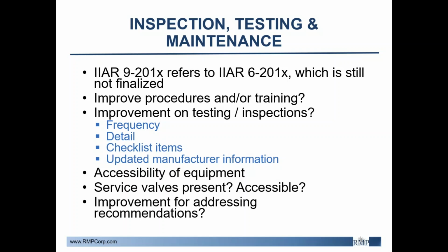If there's a way to do that, there's a way to improve testing and inspections based on frequency or detail, or adding things to your checklists to make sure that all the equipment's being hit, or maybe there's known faulty valve types that you need to add in as more frequent, things like that, or if the manufacturer comes up with updated information as far as maintenance.